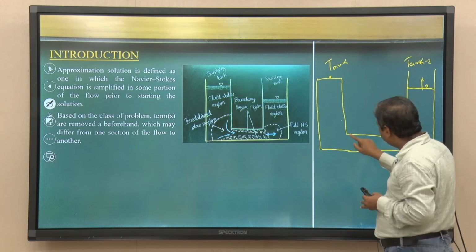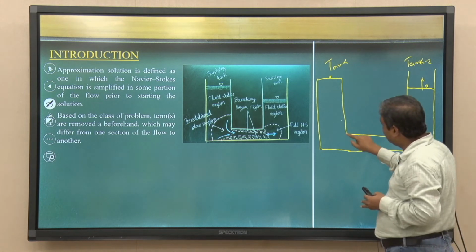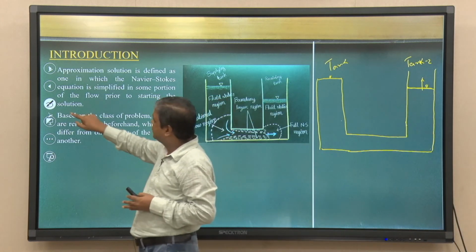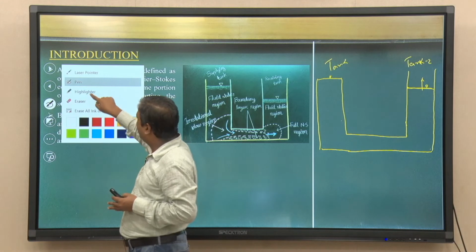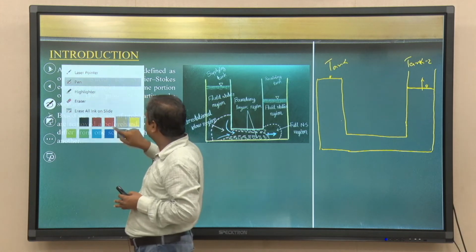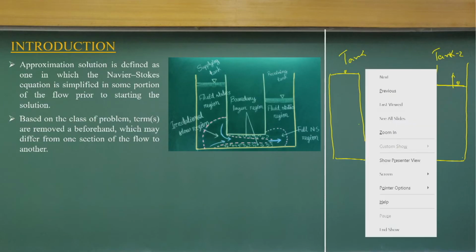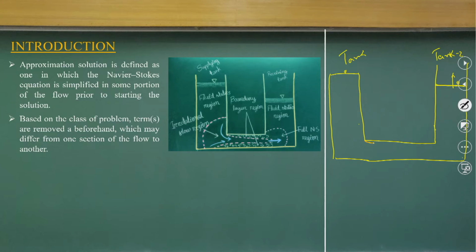That means very close to the flow there are regions where, to maintain the no-slip boundary condition, you will have very thin layers which will be viscous and have rotation, because near the wall, with the no-slip boundary condition, velocity has to be 0.